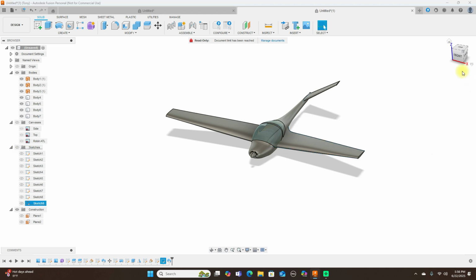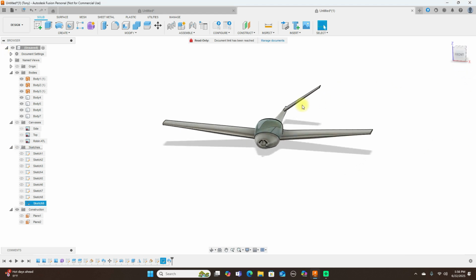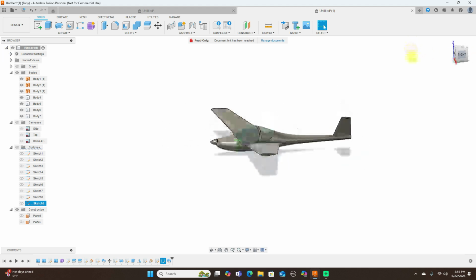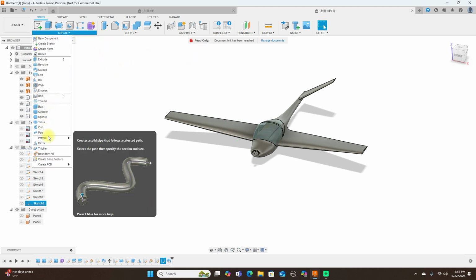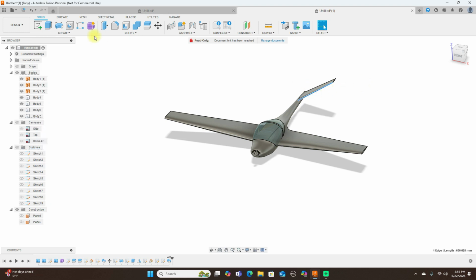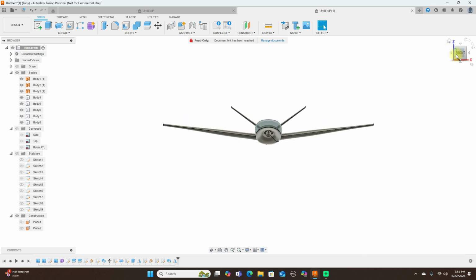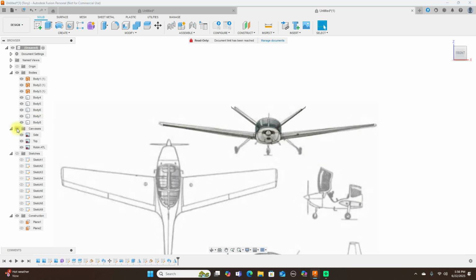Turn the sketches off. Now I can make this thicker by just going back and editing that sketch, but I'm not going to. You guys know how to do that. It just shows you how to do it, so it'd just be a waste of time me doing it. So what I'm going to do is go ahead and mirror this. And the mirror plane is this. And make it a new body also. And click OK. Okay. Not bad.